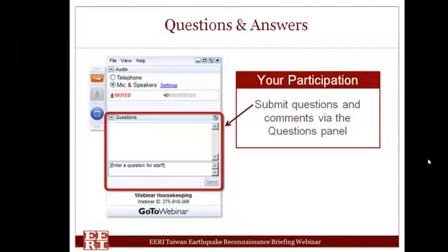This is Joseph. I went to a presentation hosted by ENCRE, and it says that the transmission lines damage that was described before mostly are not related to ground deformation. They are always damaged or determined to be damaged by transient motion or peak ground velocity. However, there were two areas of the water distribution line that showed a systematic damage pattern. And the water department thinks that those distribution lines may be damaged caused by liquefaction. But there were no ground displacement damage for the transmission lines. Ground displacement damage only occurred at the distribution level. That's what I got from the presentation offered by ENCRE.